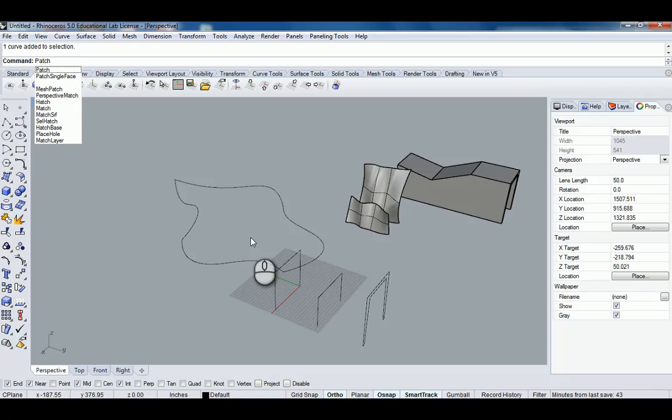It's less accurate than the other surface creation commands, but sometimes it's very useful to literally patch a space. Say you're creating a landscape or a model that you want to print, and there's a weirdly shaped opening or hole in the surface that you've made. A patch will try to figure out the easiest way to span that hole, even if it requires double curvature or doesn't have enough inputs. It will try to create a surface that fits that window.